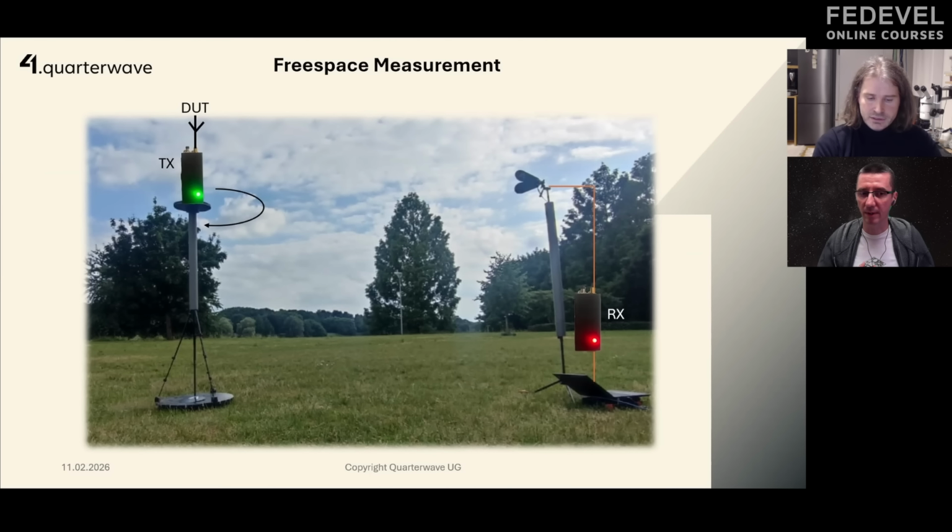So now, explain a little bit more. It means, for example, you are using the standard Bluetooth Wi-Fi output, and in one mode you are sending out the signal, and in the other mode you can read how strong the signal is. Exactly, I measure the RSSI. At the moment it's a fixed channel, but to see how the antenna is working, it's enough.